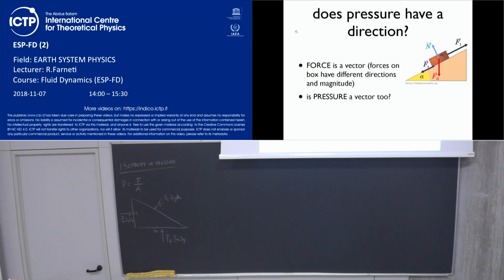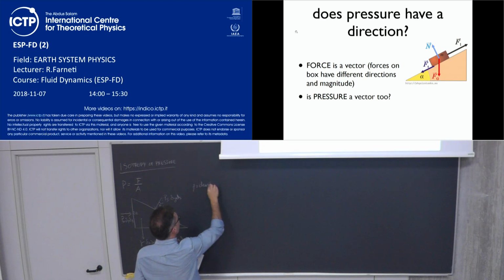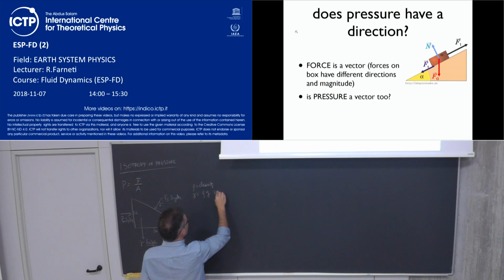Okay, then there's something else acting on this infinitesimal volume of fluid, which is its own weight. We're going to make the assumption that it's infinitesimally small, so weight is going to be infinitesimally small, but nevertheless, we can start with the general case of a delta x, delta y, delta z over 2, where I have defined rho as density and gamma to be the specific weight.